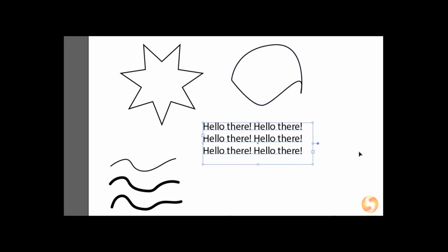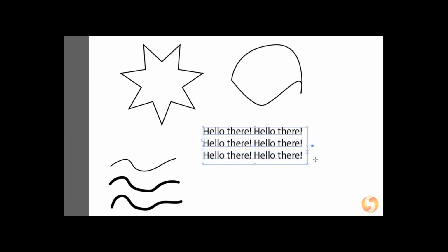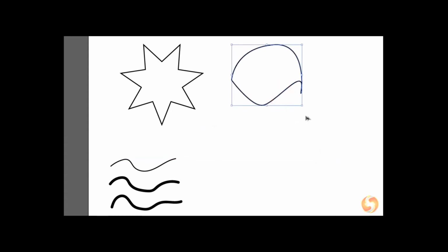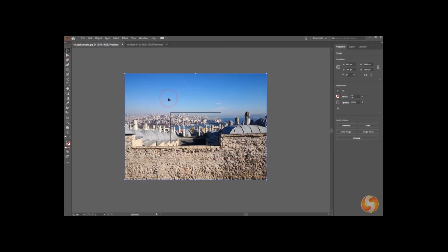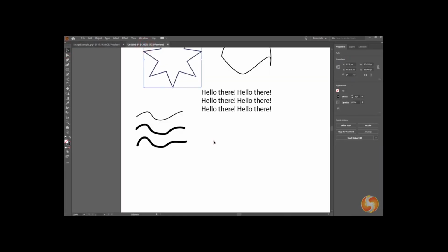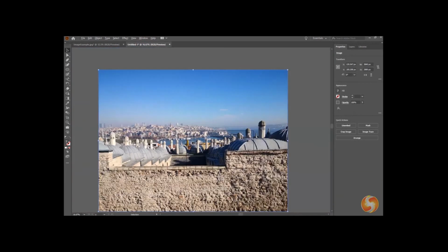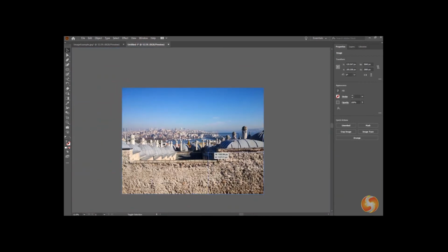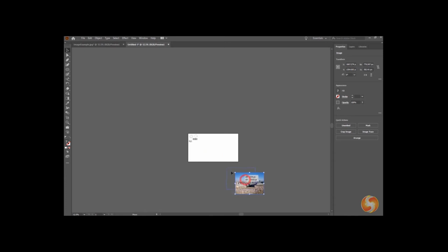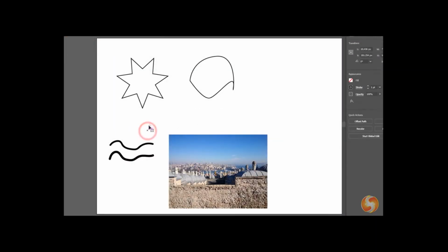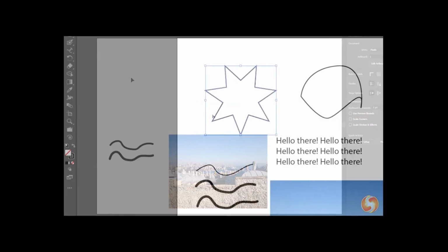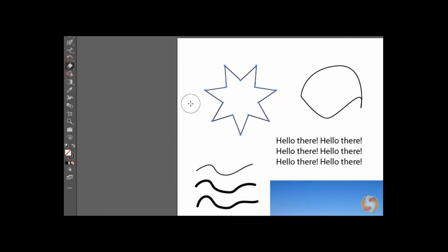Use Ctrl or Command and Z to undo, and use Ctrl, Command, and X, C, and V to cut, copy, and paste any selected object. You can cut-paste any image to import it into the current document. Its skeleton will be simply its basic contour, which can be used to move and scale the image itself. Use the Delete key to remove any selected object, whereas use the Eraser tool to delete any part of it by brushing on it.